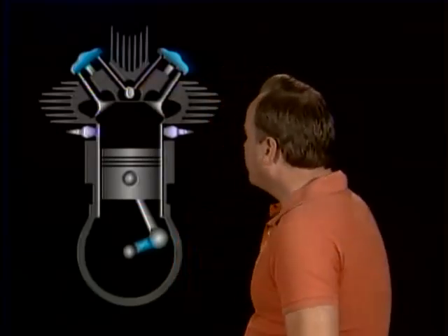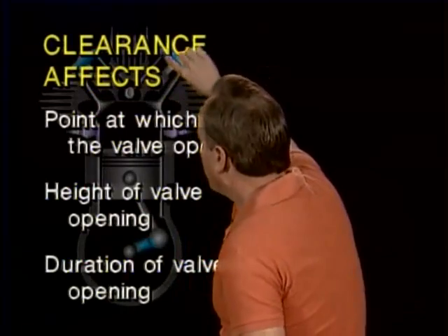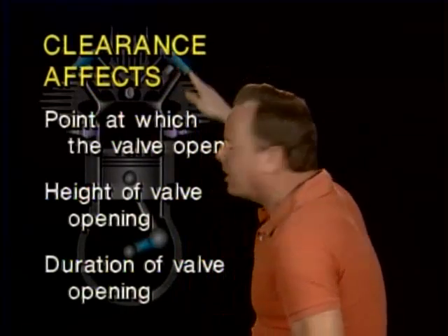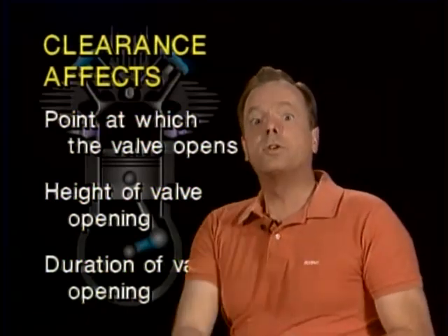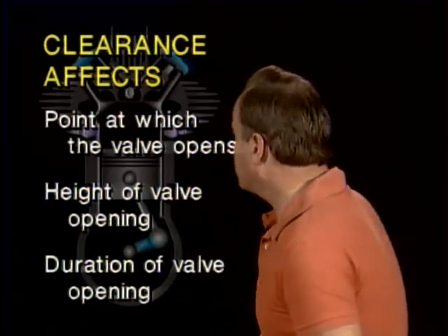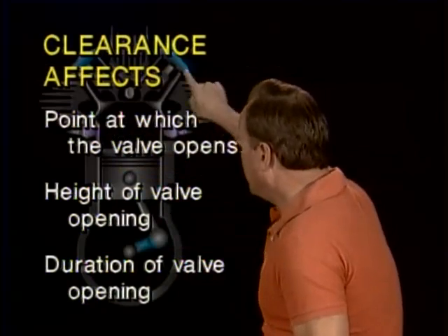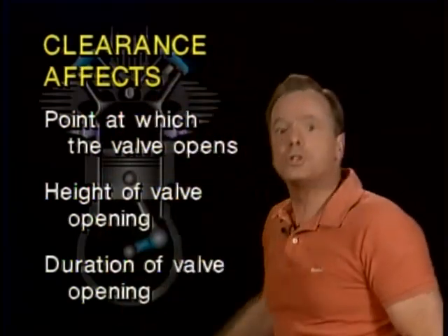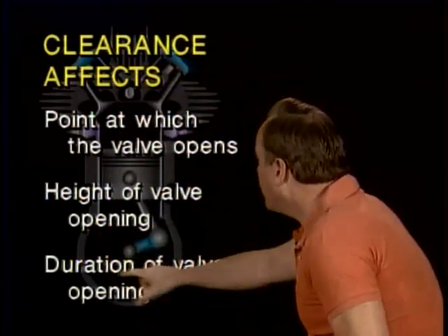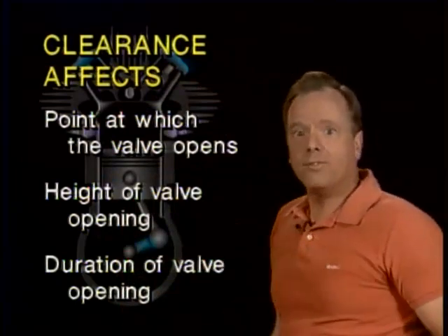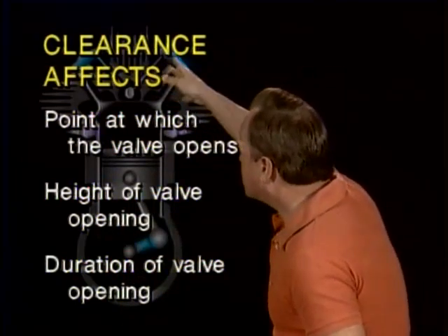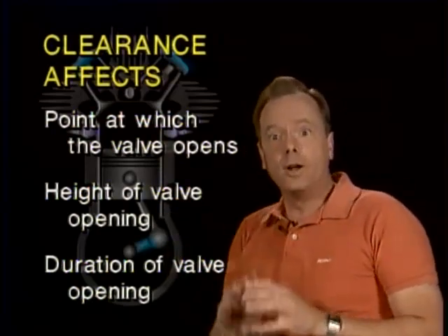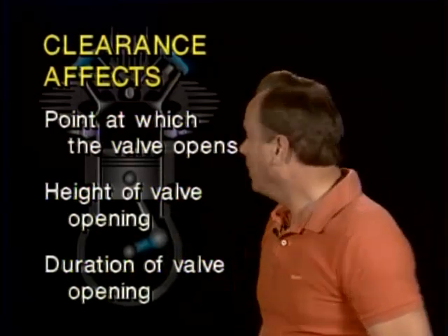Now, what does the clearance between the rocker arm and the valve tip affect? Here you have the rocker arm and the valve tip. What does the clearance at that point affect? They want you to know it's pretty doggone important because it affects the timing, the point at which the valve opens, the height of the valve opening, in other words how much the valve opens, and the duration of valve opening, how long that valve is open. So if you have adjustable valves, the clearance between the rocker arm and the valve tip is very, very important. That's the whole idea of that.